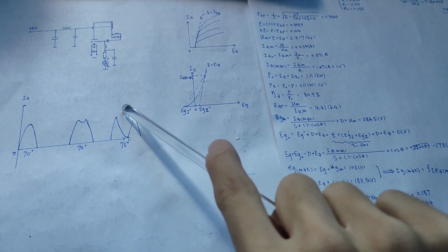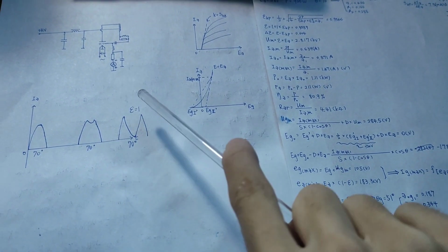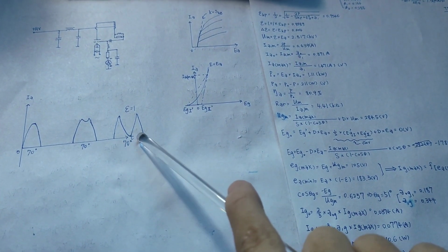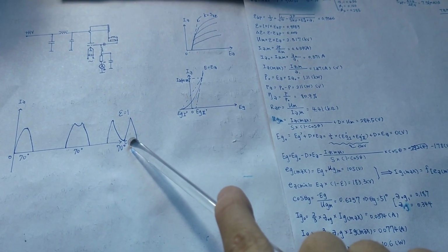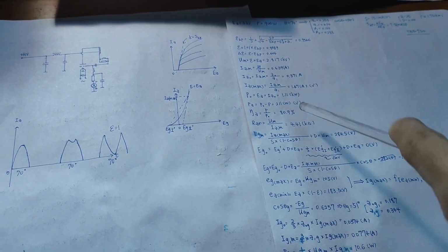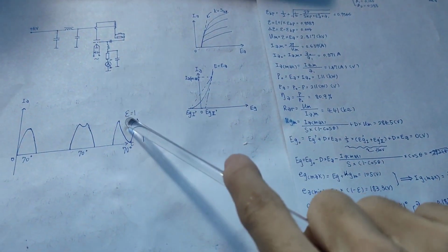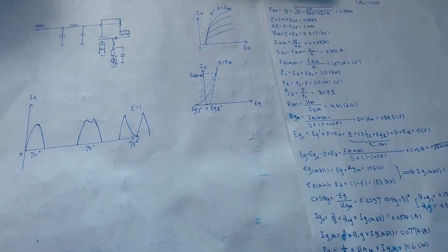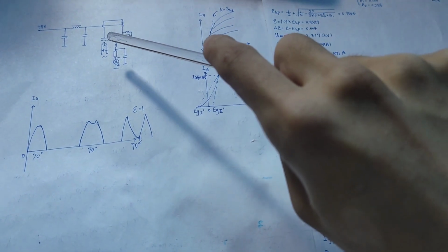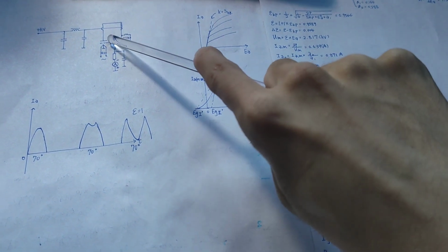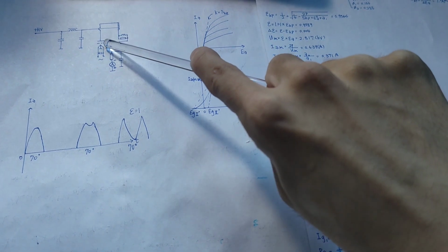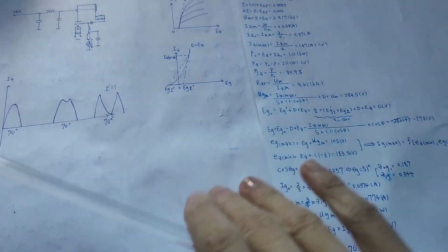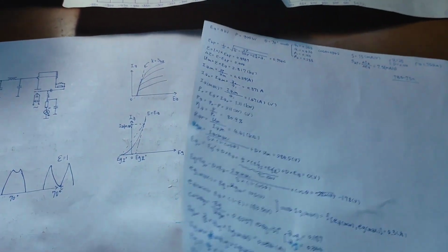This is not a small part, a very large part. That means the anode voltage actually touches nearly zero, which we will see in the calculations soon. And in that way, we can get a very high efficiency of the tube. But that means we need to have the grid driven at a much higher voltage or potential than the anode. So let's start our calculation.